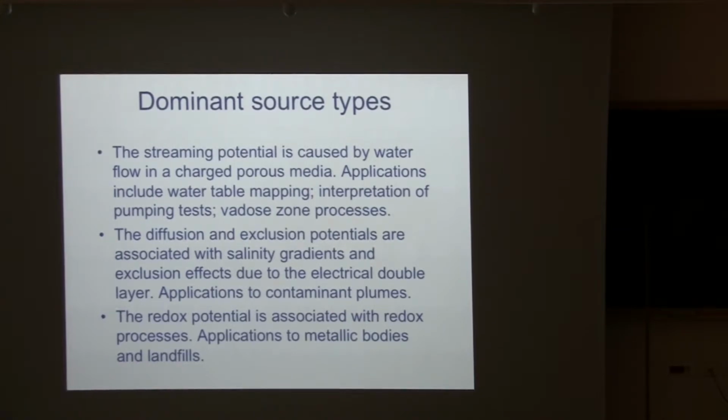They are going to be dragged with the water flow. This is creating a charge imbalance, and you're going to get a current, and this current has a potential associated with it, and you can use it to say something about groundwater flow or vadose flow patterns.